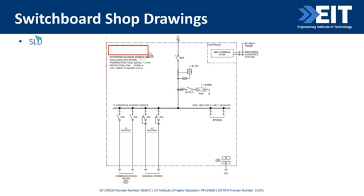So this is an example of a design drawing where a lot of that information is shown. So we've got an isolator, 3 phases coming in. We have a kilowatt hour meter. We also have a surge protection or a surge diverter. This design has a 160 amp bus bar, fault withstand rating of 15 kA, and its size is 24 poles. So we would want to check all those things on the shop drawings.